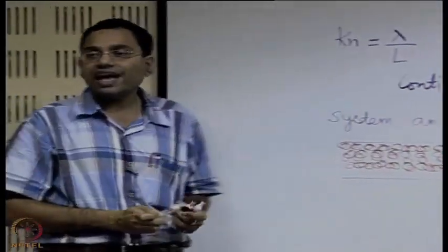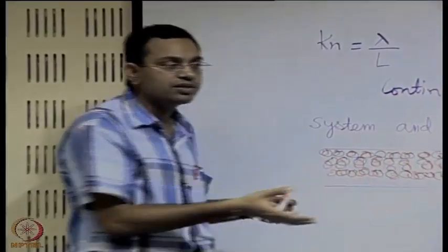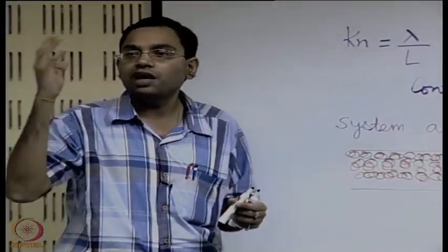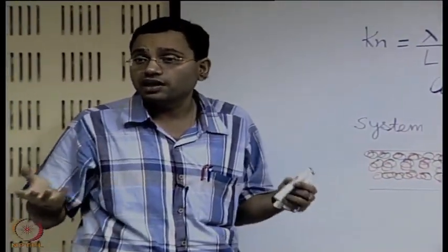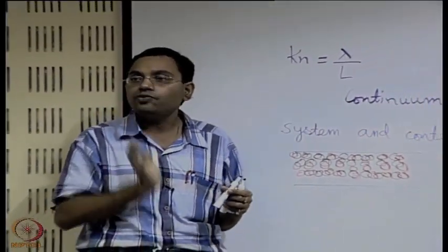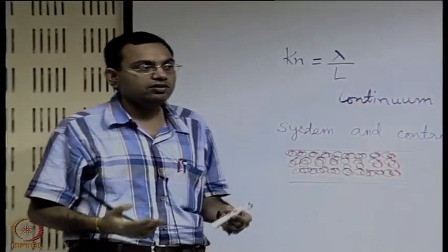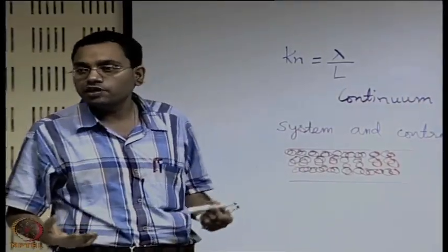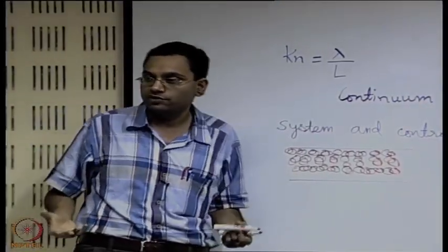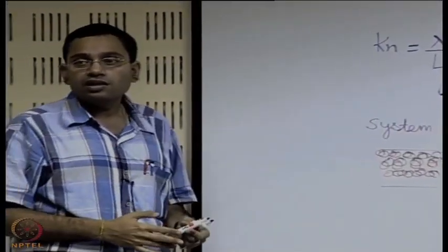In such a situation, if you want to track the motion of these particles or individual molecules as something of fixed mass and identity, it becomes difficult and tedious, because then you have to put a tag on individual entities and follow them as they move. This kind of approach, the so called particle tracking approach in mechanics, is known as the Lagrangian approach. In fluid mechanics, it is many times not convenient to follow that approach.